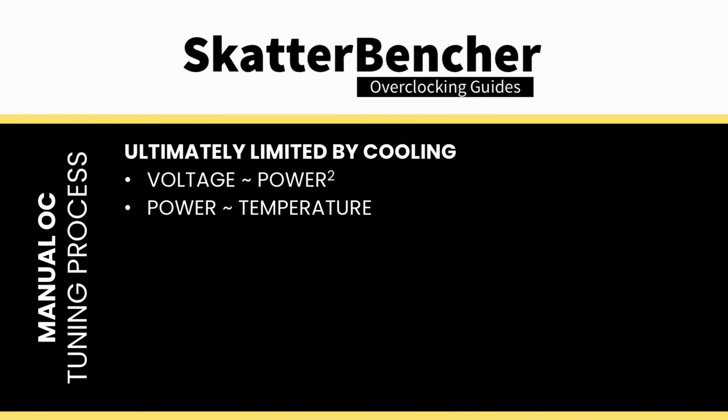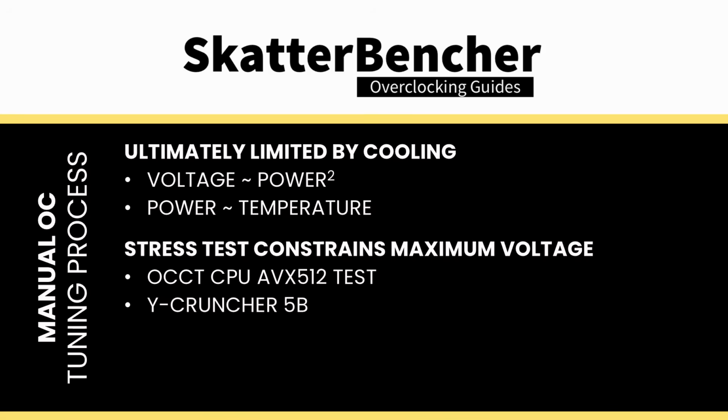It's with that last thought that we kick off our manual tuning process. Our limiting factor will ultimately be the cooling solution, as power consumption increases exponentially with operating voltage and temperature scales somewhat linearly with power consumption. The maximum voltage will be determined by the application we are tuning for. So the first step in our tuning process would be deciding on the stress test representing our worst case scenario.